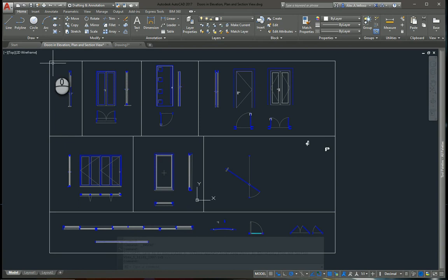But you cannot have different objects with different measurement system. You cannot have with imperial and some metric, or even imperial in inches, the other drawn in imperial foot. Because once you try to import, it will import all in different scale. It won't be proportional to the plan.